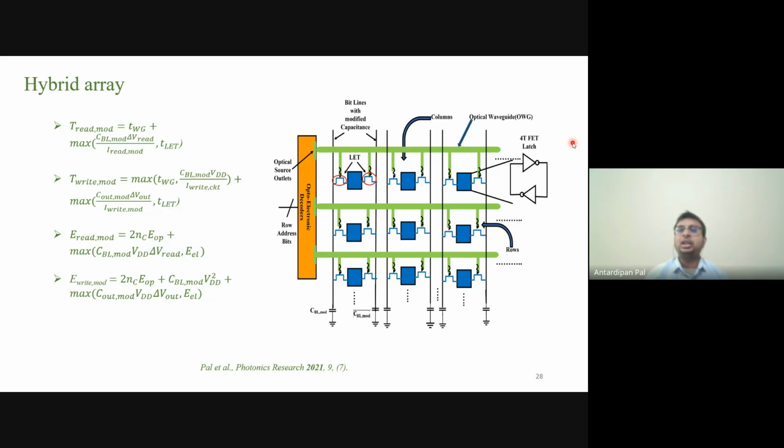So the overall delay will increase by 1-2%, tops 5%. An insignificant increase of delay, doesn't matter. Energy, same thing. Light travels by total internal reflection, with no dissipation of energy. That's why we use optical fiber cables in communications, right? In our internet, that's the reason we use optical fiber cables. Almost theoretically no energy dissipation. There are dissipations due to some non-idealities like surface roughness, surface scattering, non-ideal coupling, but those are very small compared to the actual RC dissipation. So almost no energy dissipation, almost no increase in delay, right?